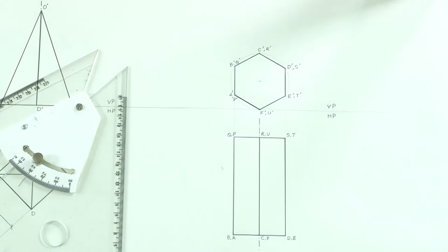Just imagine where you are going to see the parallel faces. In case the parallel face is going to be seen in HP, you will start drawing from HP. In case the parallel face is being seen in the VP, you will start drawing in the VP. That's a clear and simple rule, because that is how you will be able to draw the true sides, the true sizes and the true shapes of the solids.